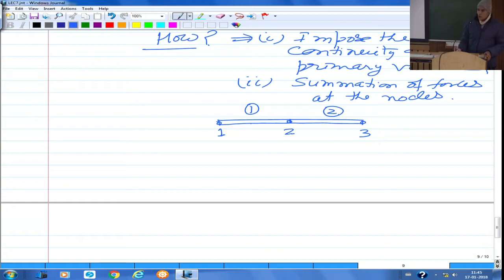Now when you look at element 2, because 2 is one side, there is a left side element number 1 coming, and a right side element number 2 coming. And in both, that means the right end of 1 and the left end of 2, we had some u, that is a degree of freedom at that node, either of the second node of the first element or the first node of the second element. Now what we are going to say is that the value of u here, whether you consider u2 of this or u1 of this, let us say that they are the same.